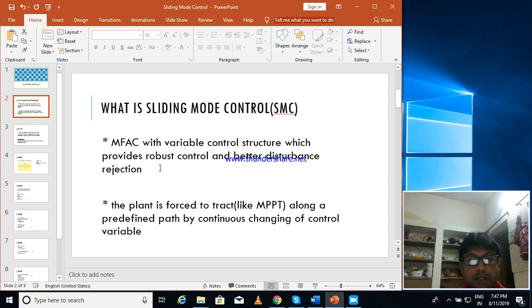Likewise, you can take one example of MPPT, where we always want to fix the maximum power to be delivered to the load by changing the impedance between the source and load by matching, which follows the maximum power transfer theorem. That means by changing the duty cycle of the DC to DC converter, we will always make the input and output impedance a complex conjugate, so that the maximum power can be transferred at the output.